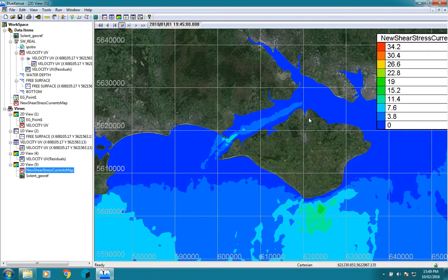Okay, finally in this part we're going to look at sediment mobility maps, and they basically give you a feel for spatially over the area. If you had a certain type of sediment, what is the likelihood of it moving? If you have a value of between 0 and 1, this suggests there'll be no sediment movement. 1 to 8 is saltation, greater than 8 is the material is going to be suspended.